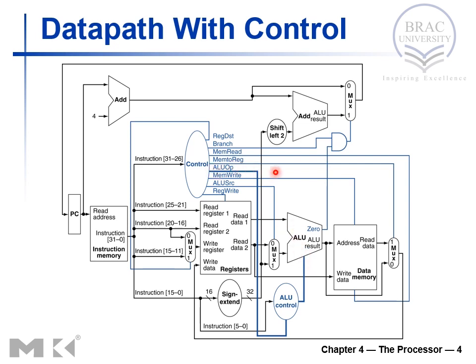And then memory to register. This is for the write back operation. When we are performing an add operation or R-type operation, then 0 will be enabled, and when we are performing load, then port 1 will be enabled. And then memory read. This link will carry the enable signal when we are performing memory read operations, so when we are executing a load instruction, this signal will be enabled. And then this is for branch instruction execution, and then register destination is this. So these are the control signals that are generated by the control unit.